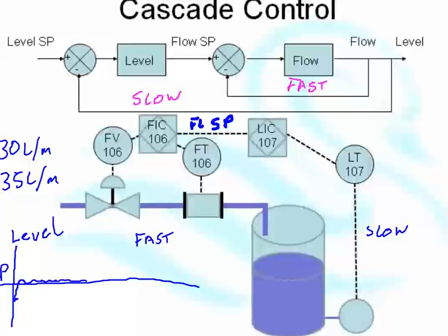When things change, and things do change, everything changes, nothing stays the same. Valves are always being serviced, outside air temperatures are constantly changing. When things change, cascade control responds much better because we get the characteristics of the fast loop being put onto the slower loop.